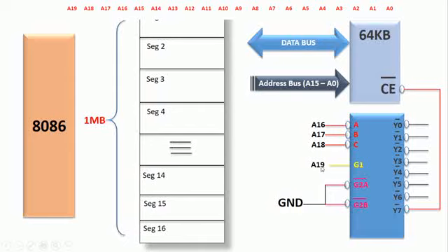I'm using the A19 to activate the active signal, and two active low signals are there now. They are directly connected by connecting that one into the ground signal, because it is 0 volts. So A19. In order to choose the Y7, A19 is always the one. A18 should be 1. Means we are supposed to give the 1 1 bit combination. Three ones are there at the input. Then only Y7 is selected.